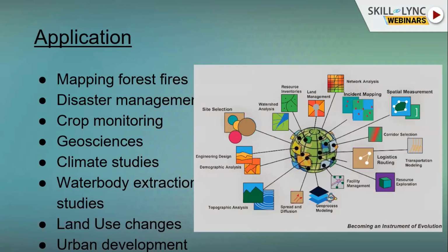We can do inventory mapping, we can do management, we can take soil, topographic conditions, NDVI, LULC, drainage, or principal component analysis. We can integrate all those parameters in the GIS environment, and we can see how GIS is helpful in crop mapping.